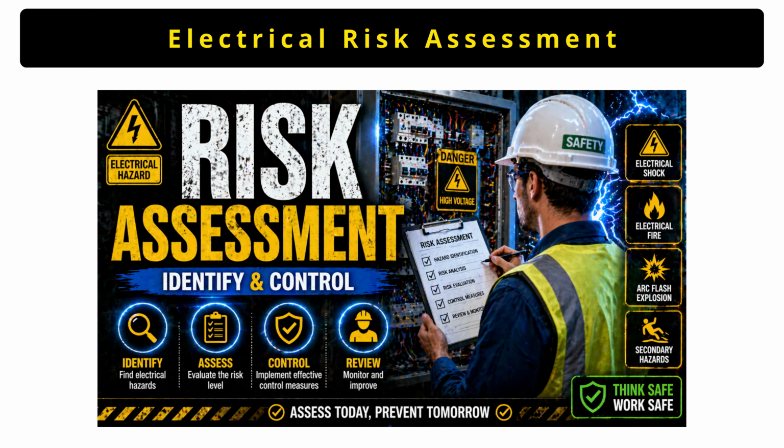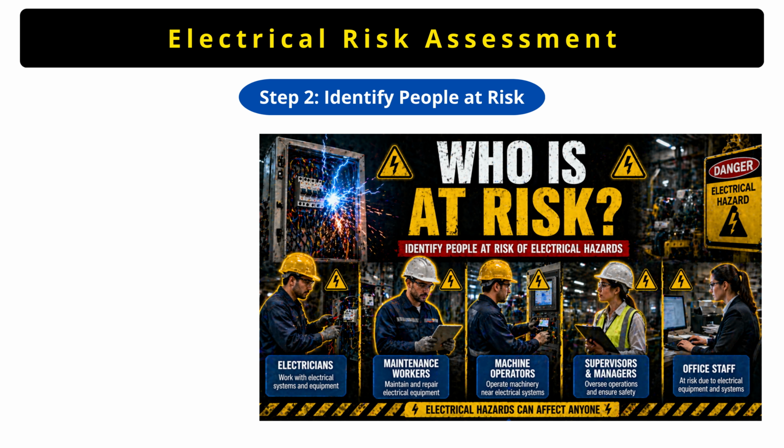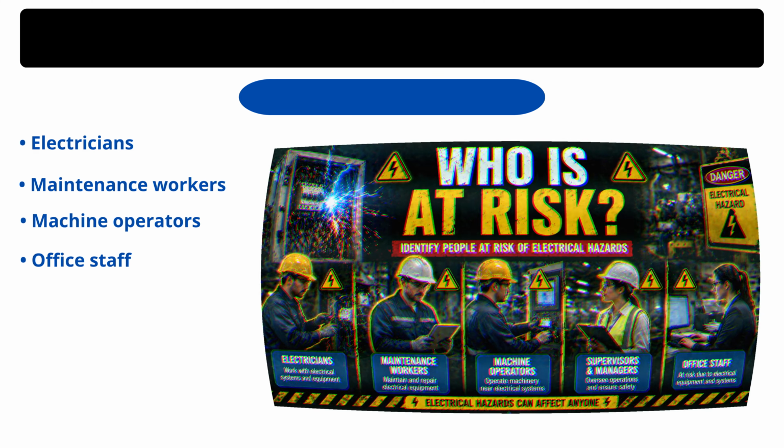Now let's talk about the electrical risk assessment. Electrical risk assessment helps identify hazards and implement controls. It follows these steps. Step 1 is identify hazards. Examples like exposed wires, overloaded sockets, faulty equipment. These are the hazards we can identify. Now let's move to the second step, which is identify the people at risk. So the electricians, maintenance workers, machine operators, office staff. So these are the people who are at risk.